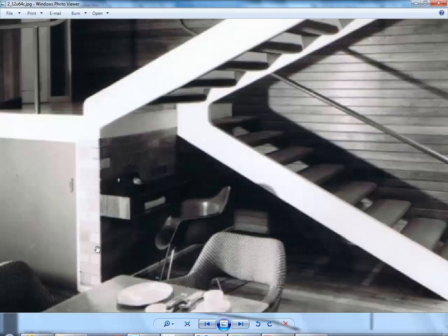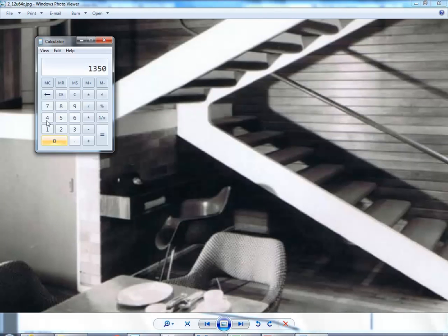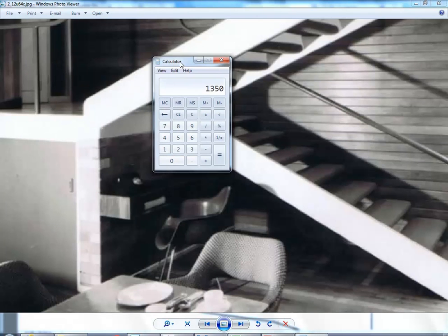1, 2, 3, 4, 5, 6, 7, 8, 9, 10, 11, 12, 13, 14 courses. So, do you know how high a brick is? Yep, not bad. So yeah, 75 or 76 if you want to be precise. It's actually a tiny bit less than 76. Yeah. So with the mortar, that's 86.